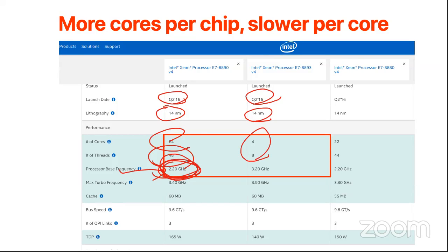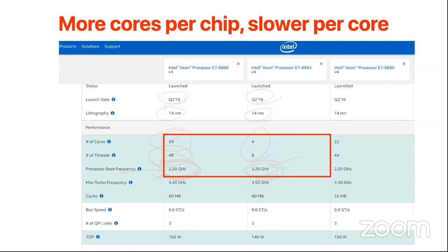However, if you have fewer cores, you can run at a higher frequency because the power budget of your heat dissipation is limited, and the higher the frequency, the higher the power. So if you want high performance, instead of continuing to boost your clock rate, you have to make processors that are slower but with more cores. That's also because of the limitation of power.